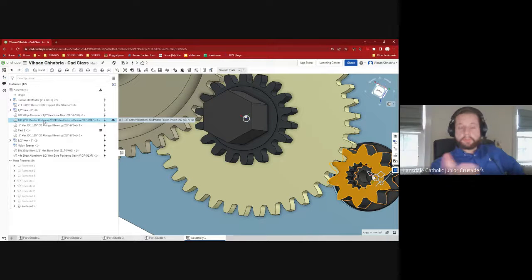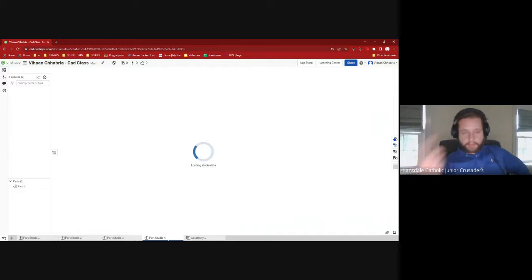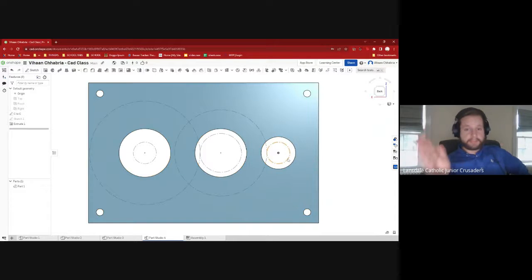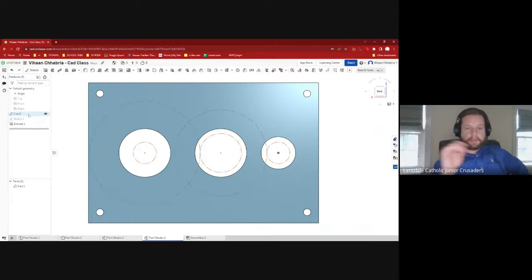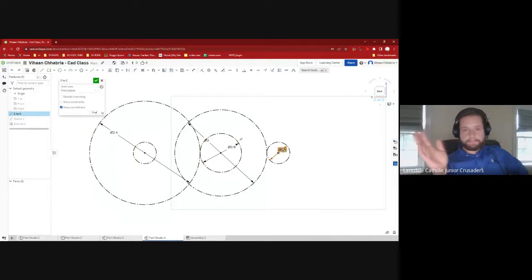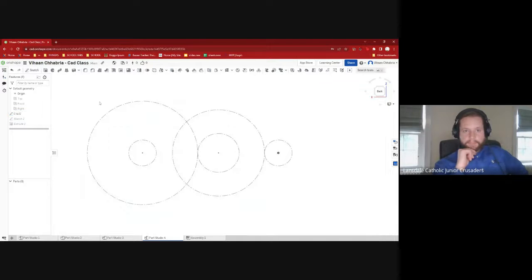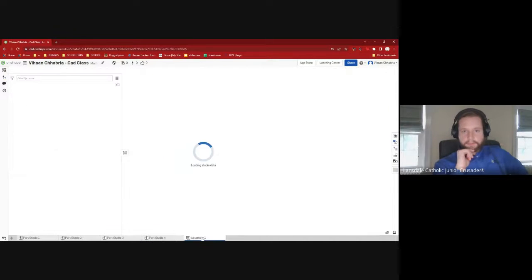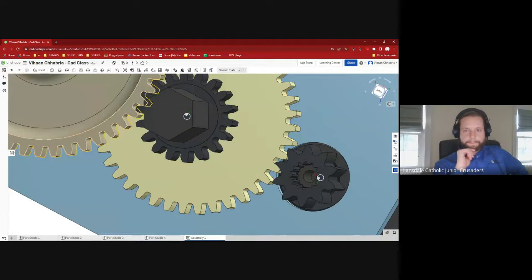Yeah. So what you need to do is in your layout sketch, you need to change it from 10 divided by 20 to 12 divided by 20, even though it's a 10 tooth gear. It's a little bit weird. They're very specific gears, and it only works for the very small ones. So yeah, make that 12. Then if you click enter, click the checkbox, and go back. Now it should be meshing correctly, or should be the correct distance.